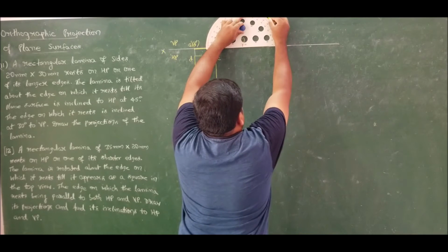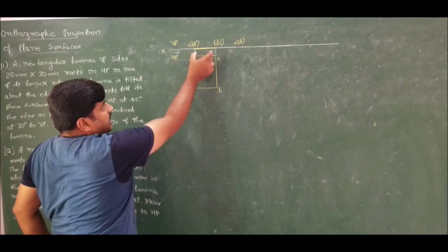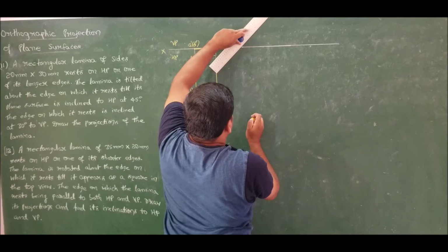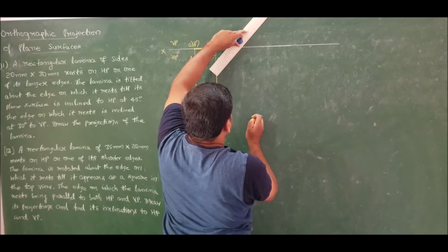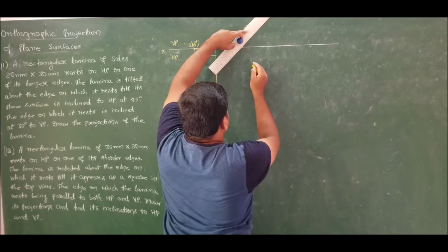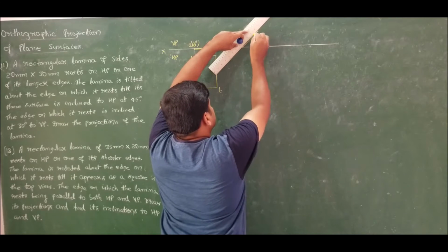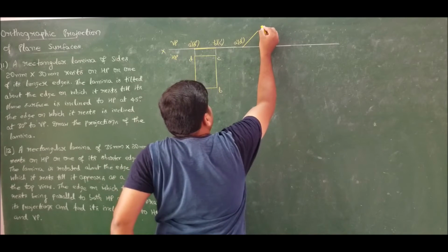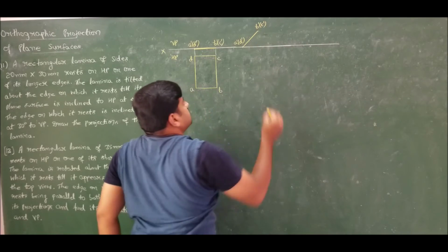Measured 45 degree. Now you know, when I took the projection, I have the shorter edge whose length is already known, which is 20 mm. Draw 20 mm at an angle of 45 degrees. Drawn. So this will give us another end, that is B dash, C dash.